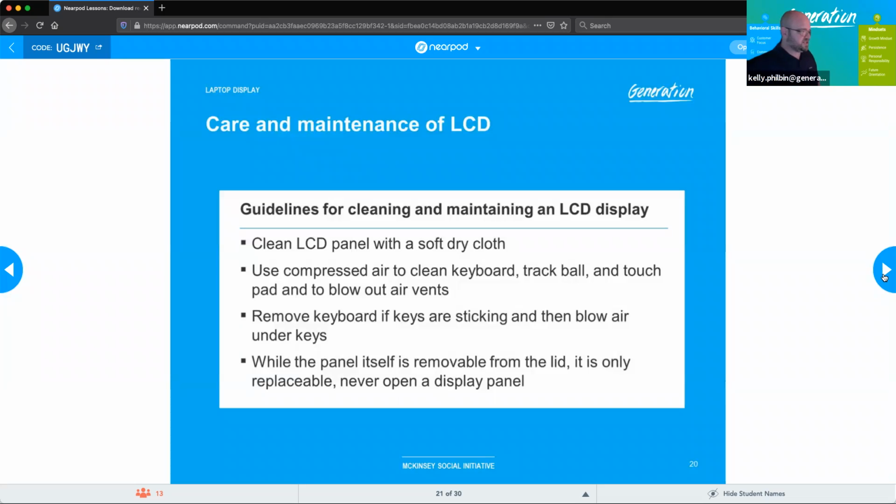And it actually has a protective layer of glass between you and the actual LCD display. On just a plain LCD, that is not typically there, which is why when you touch it, the image distorts. And if you're distorting that image, you are damaging it over time. When you do that, eventually the damage becomes so great that the image will not be able to be generated fully, or you will get dead pixels, or broken parts of the screen. And anybody with young kids, if you have a flat panel TV and they get up and they realize if they touch it and it turns all fun and pretty colors, that's all well and good until they actually break it.